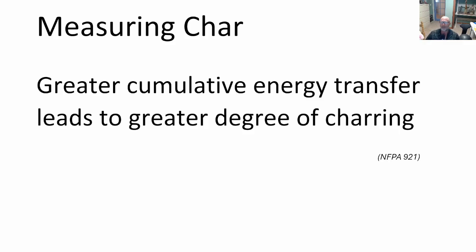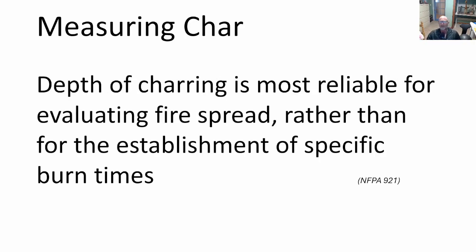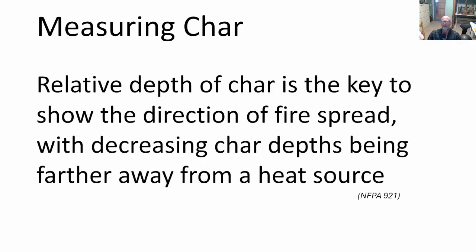But the reality is you can conclude that char depth is going to be effectively proportional to actual accumulated energy transfer over time. And you can use that as a tool because depth of char may not be the most reliable metric to be able to calculate fire time. But what it can be used for is establishing an origin, identifying where an origin comes from. So relative depth of char is the key to show the direction of fire spread.